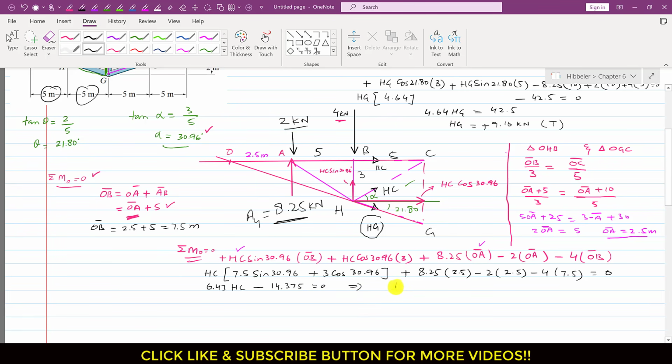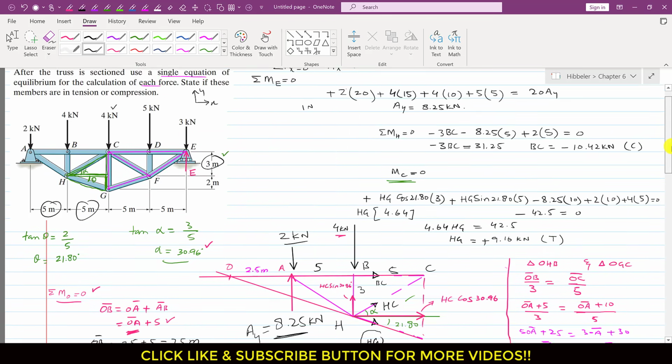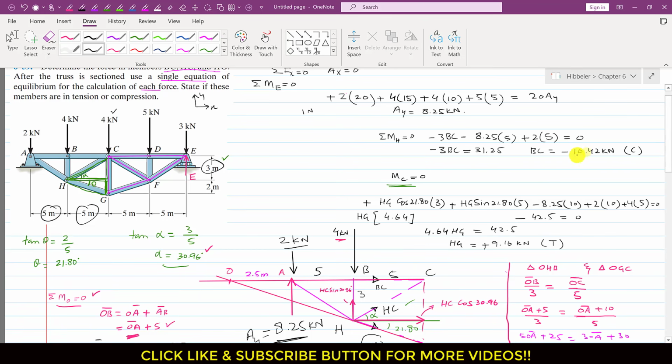So from this equation we get HC equals 14.375 divided by 6.43, which gives me 2.24 kilonewton. Again, the sign is positive, so this means that the HC force is the tension force, right? So now we have determined BC force, HG force and HC force, which is the required solution of this particular problem. I hope you people would have understood this very important problem, right?